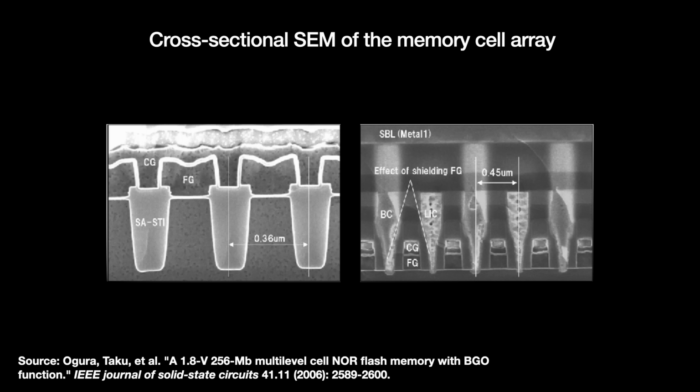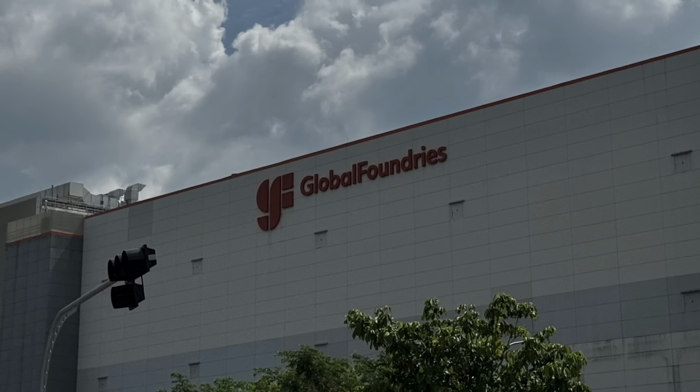Anyway, so eFlash being NOR means it cannot achieve the same density as NAND has. It also does not write as fast as SRAM or DRAM. Its cells also suffer the same endurance issues as discrete flash memories, breaking down over repeated write cycles. And same as eDRAM, there is a fabrication cost. It requires an additional 6 to 8 mask steps, which can be more than eDRAM. You take on more yield risk.